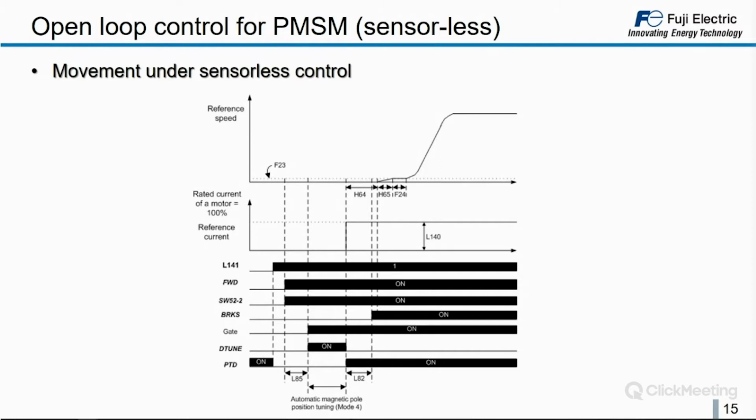You press the up or down button of the inspection button. The controller will give the run command. We will close the contactors. And after closing the contactors, the inverter is going to perform an automatic pole tuning, because we want to know where the magnet is placed.